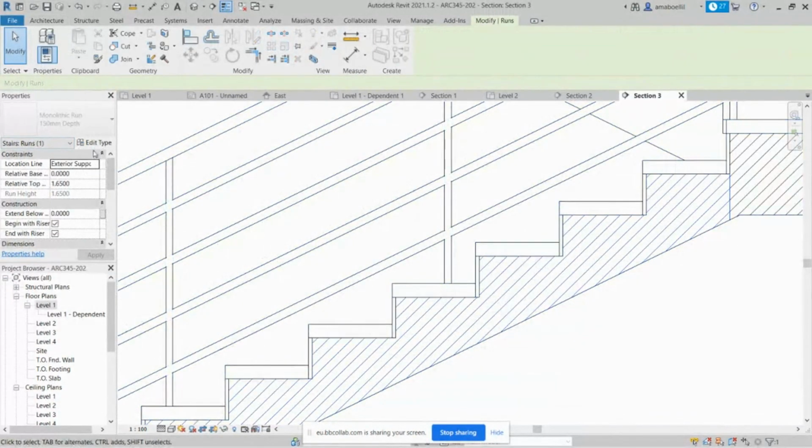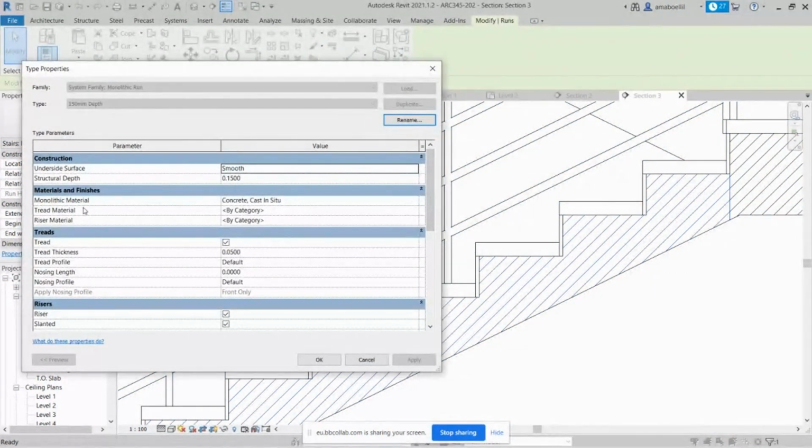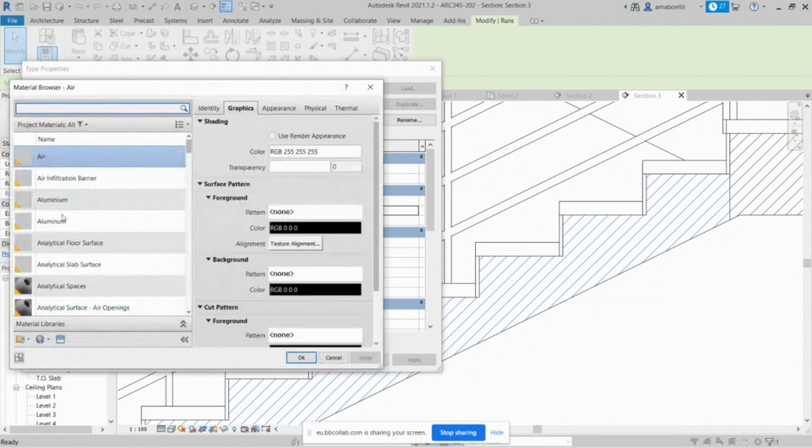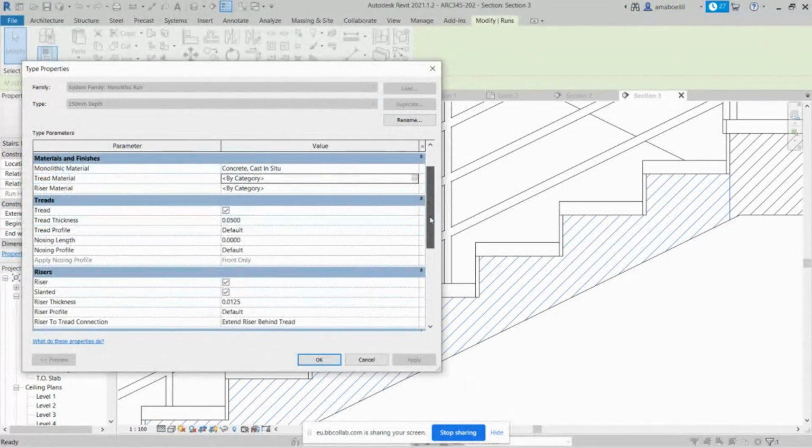And pay attention, I picked the run in order to have this drop menu show up for me. It also gives you the material of the thread and what the thread riser is. Also, you can come here and it will navigate you to the material setting that we already know, so that you can specify the kind of marble or granite, similar to this, so that we don't need to go into this. Then it tells you about the thickness, the thread thickness.